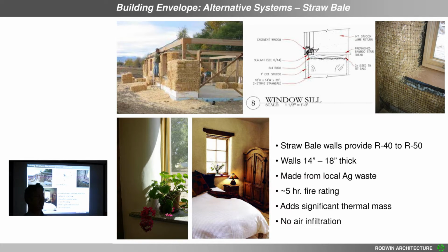And then there's a third way that's a hybrid, where you actually put studs in the walls, where you take plywood and you make giant fins, and you put them between the bales, and you use this hybrid system of essentially wood-framed walls with straw bales holding up those wood-frame walls. There are lots of different ways to do it. There's a group called COSBA, the Colorado Straw Bale Association, that's a great source for information about straw bale building techniques. Colorado is actually one of the leading states in the whole country for straw bale.